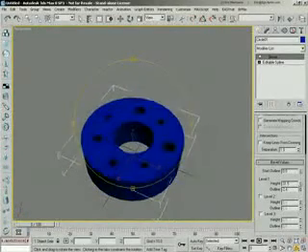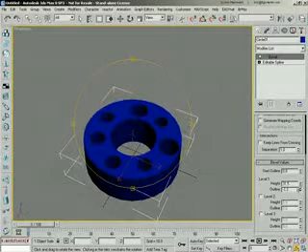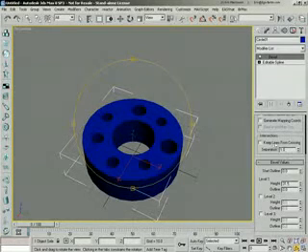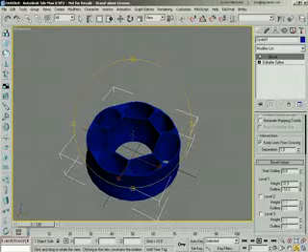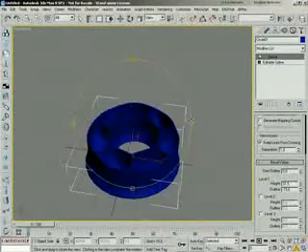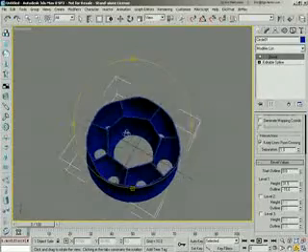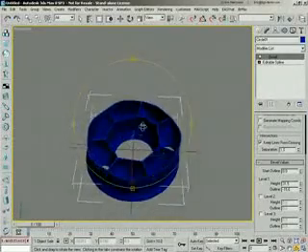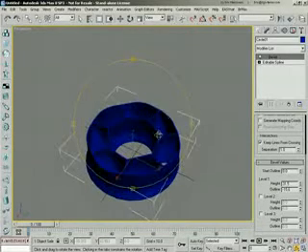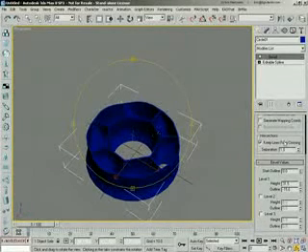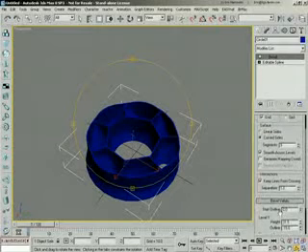It gets really crazy and objects and faces start turning inside out. What we can do is we can tell Max to keep the lines from crossing one another. So as I decrease the outline, you can see the type of shape it's creating. And so that alone is actually a pretty cool shape that you can get just by exploiting the keep lines from separating, or keep lines from crossing, and the outline option.